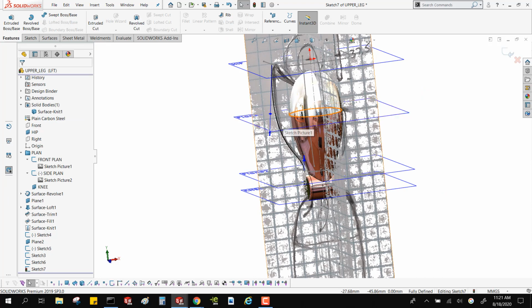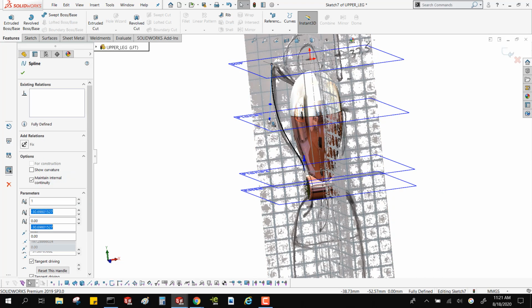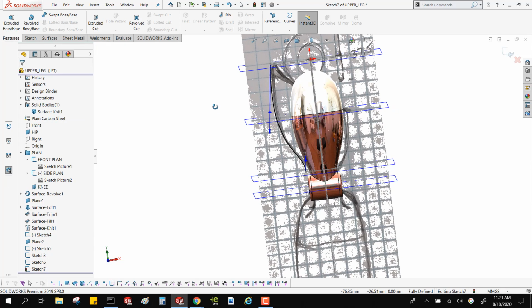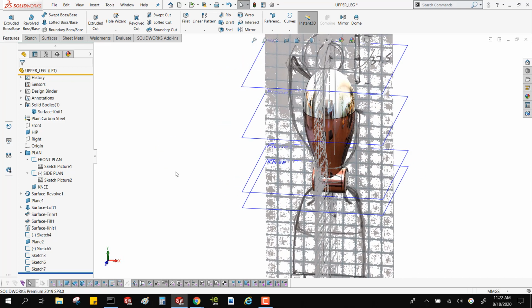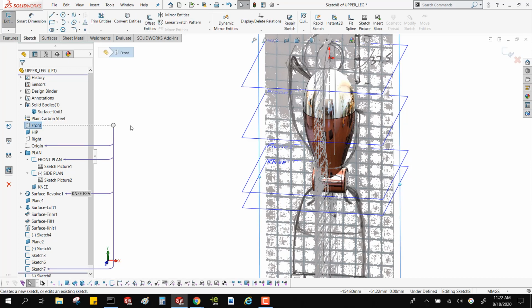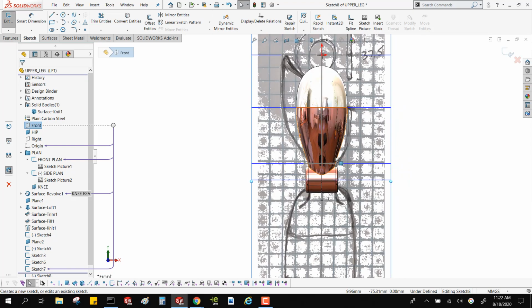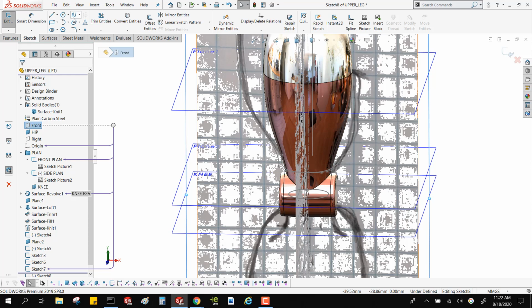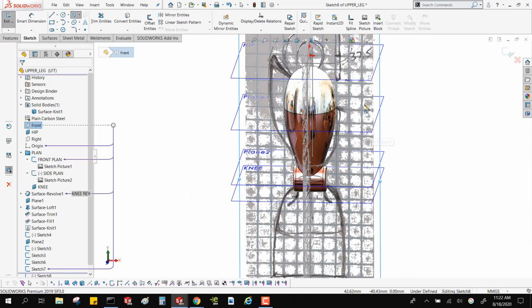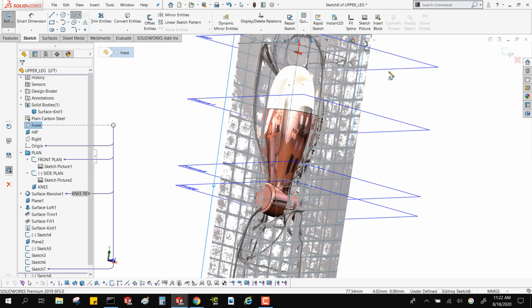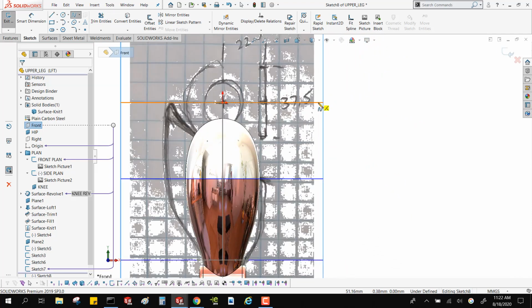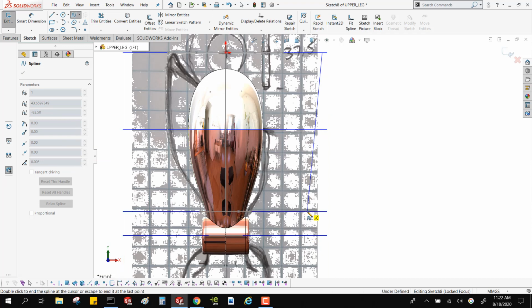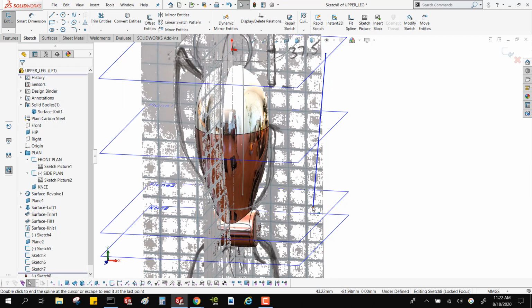You'll see that this is fully defined, but it's really not, because anyone can come in here and just start playing around with the magnitude of it. And that's just kind of something you have to deal with when you're in surfaces. They do allow you to put like angular dimensions and things like that onto spline controls, but it's really a lost cause. It's very difficult to get a fully controlled spline. Okay, one last time. Put this here and there. Line these up.